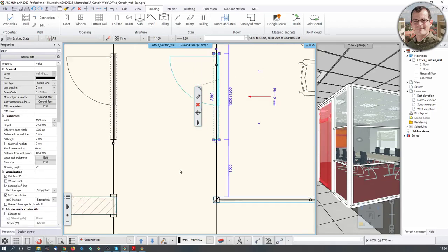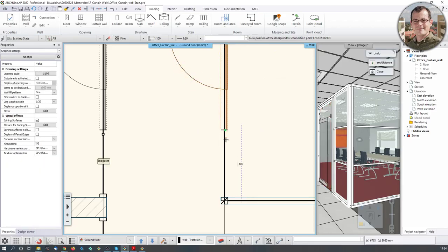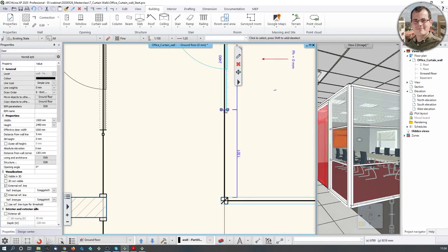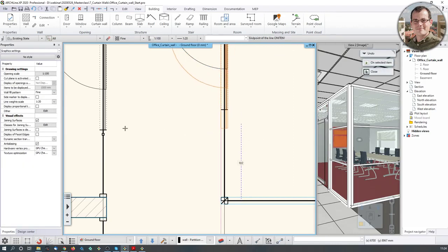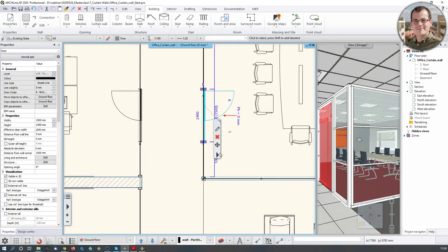And if you have put it and for some reason it's not lining up, you could be even moving it vertically. I mean graphically like that. So you can say that you want to bind to this point. So assume that you made a mistake, assume that it's here. And if you want to move it and align it with another door, just click on the door, say move, hit the shift key and move the cursor to the other door, and then they would be lining up. So again, I have to change the opening direction. I think it should be inside.